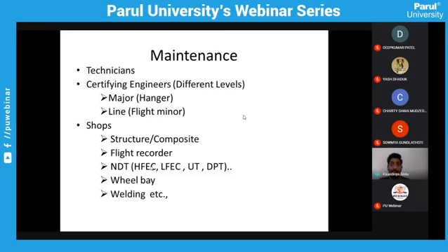And mainly for electrical components, there are ESD devices, electrostatic sensitive devices, as we call them. If you work on them carelessly, they will be short circuited. So you have to wear gloves and use an electrostatic free base, like keeping carpets everywhere you place those components. Okay, so every component has its own restrictions, which can only be worked on in shops.